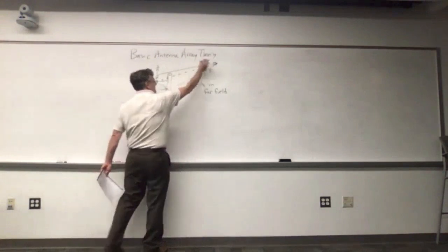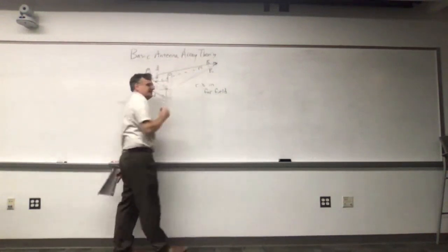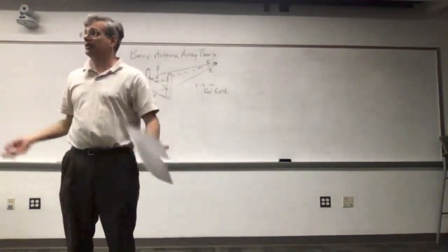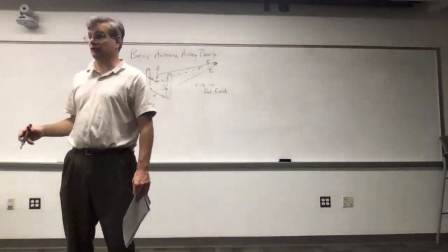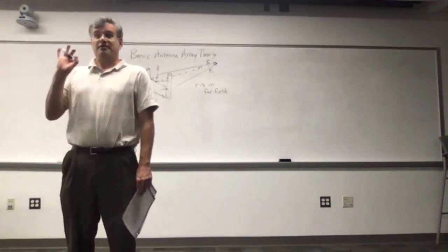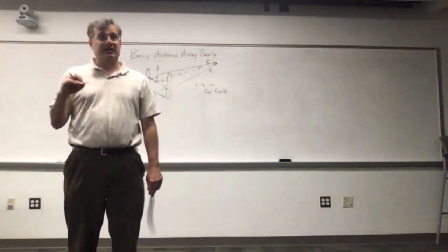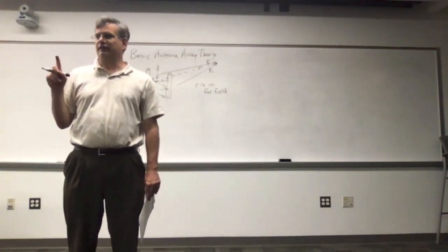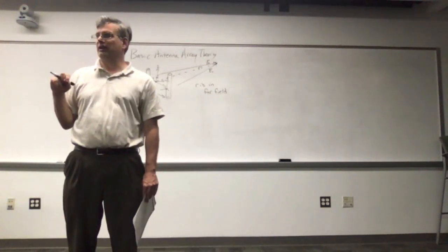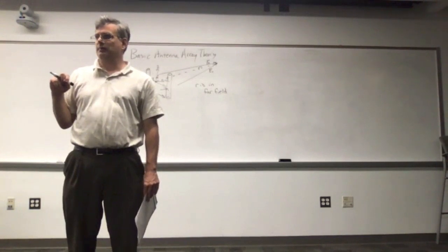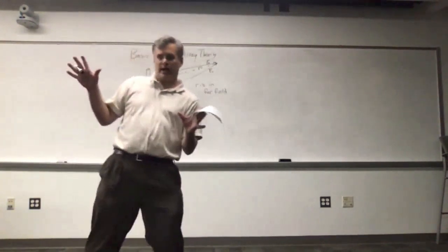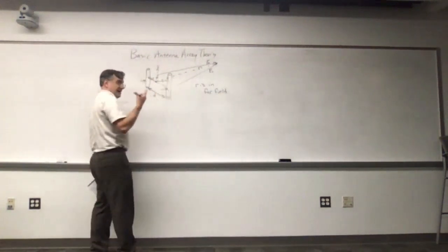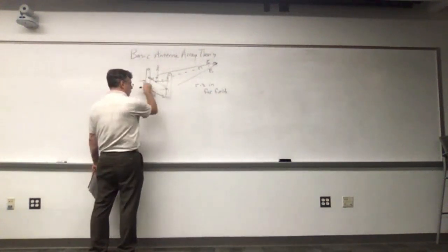These basic antennas basically radiate the same distance, so their amplitudes are going to be the same. It's in the same direction, although we're using omnidirectional antenna elements to illustrate this to start with. So that should produce roughly the same E0 magnitude field. The only thing that will change is the phase between those two radiated elements. Because, depending on which angle I observe the system, there will be extra distance at a small scale traveled by one wave or the other.